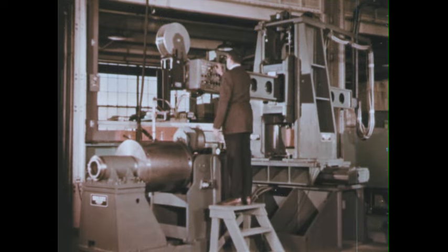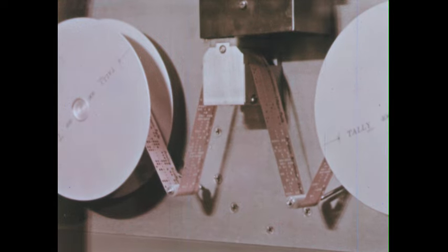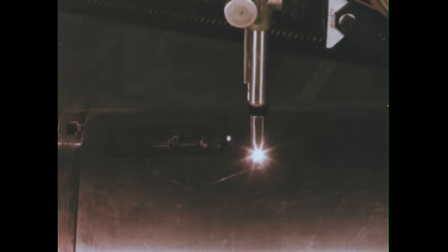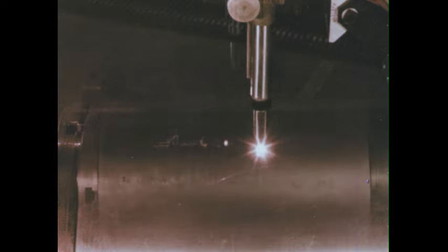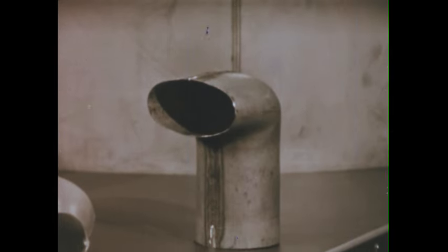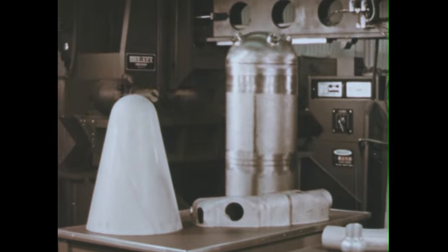The more complex fusion welding also can be performed by numerical control. The tape not only controls the positioning and movement of the arc, but also the welding factors, gas flow, current, and the like. In guiding the arc, the control permits blind welding down through one structural member to fuse it with a hidden member below. The result? A stronger weld, a member with more structural integrity, a more reliable weapon system.